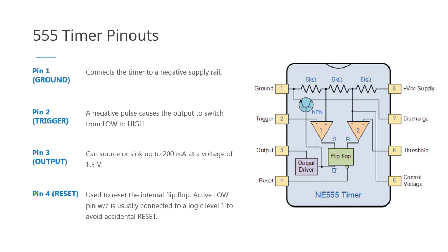Pin 2 is the trigger. So we use pin 2 as a way to connect or to activate our multivibrator circuit. When we have our design and discussion of the operation of a 555 timer, we would be able to show you the importance of the trigger, especially when you go into the course of digital logic circuit design.